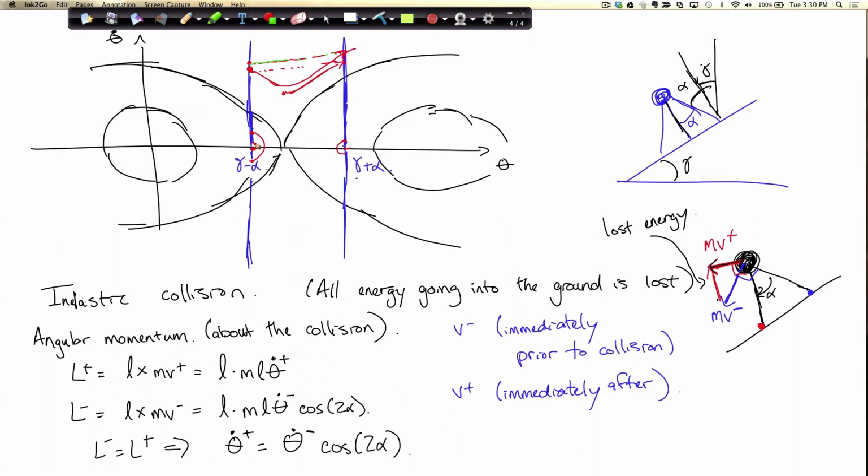It's actually pretty subtle, though. To call that a fixed point is tough, because it's only a stable fixed point in the sense of undergoing infinitely frequent collisions. That's called the Zeno phenomenon. It's one of the nasty points of hybrid systems. So that thing sitting still is in the simulation. When you see multiple zero crossings, you see that little warning that comes up every once in a while. That's it saying, I'm finding every time I simulate a step, I see lots of zero crossings. And then it can also go backwards. It can also be over on this side here.